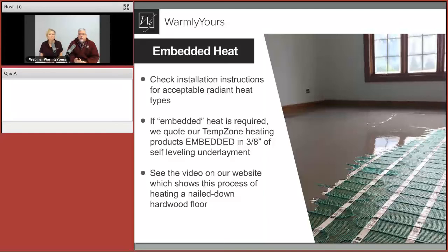It can go under flooring, and also see if it really has R value or not, because they'll say, oh, it reflects most of the heat. It reflects 99%. But what people want to know is, does this have an R value of 10 or does it have an R value of 0.1? So check for the R value. It makes a big difference. All right. Good point. Thank you for the question.